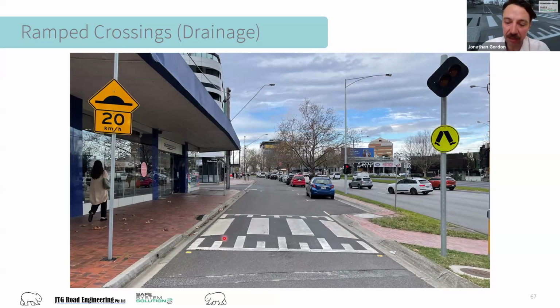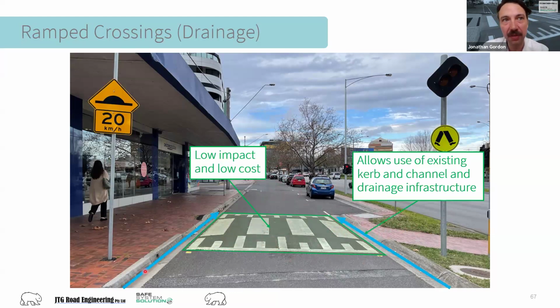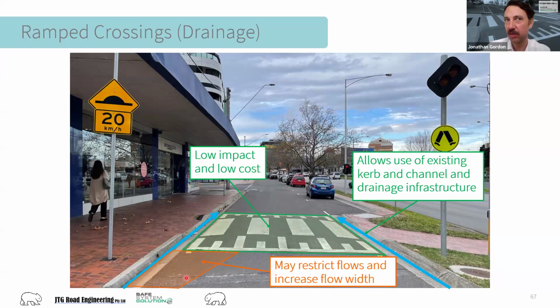What I'm talking about here is a great cheap system because it is low impact and low cost, but what it also does is enable curb flows to operate as they currently were. In a scenario where your curb is working nicely, this still works pretty nicely at a drainage level. In terms of the maintenance burden, I can see a bit of leaf litter built up here, but I don't think it's heavily influenced by the presence of the raised safety platform. These are fairly low maintenance because they're sweepable, and heavy flows of water would generally flush these out clean.